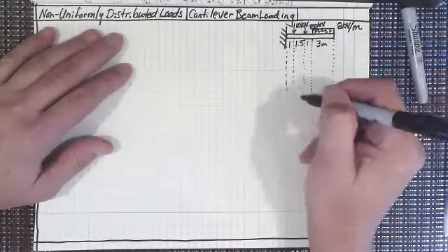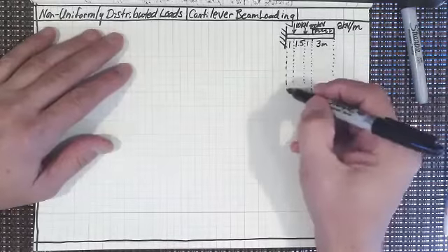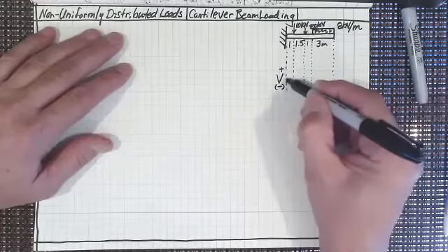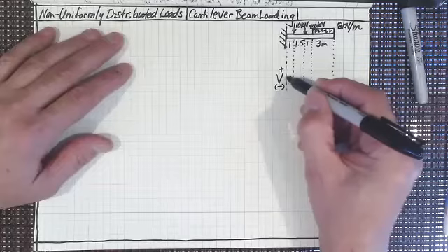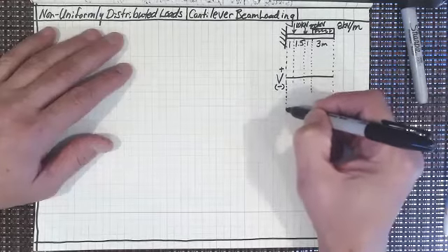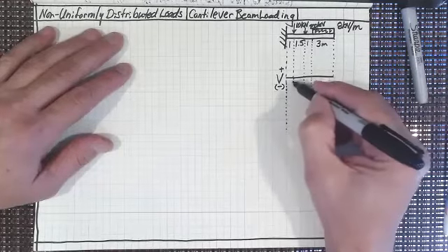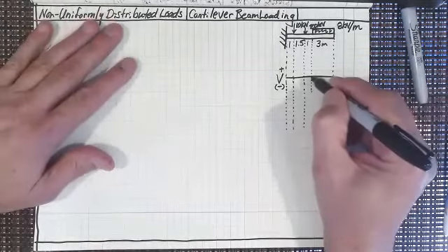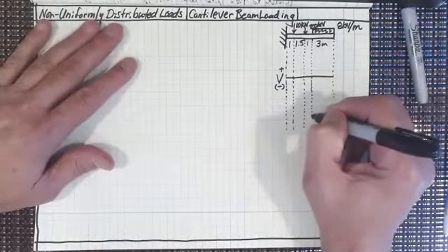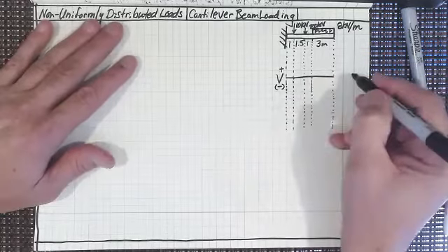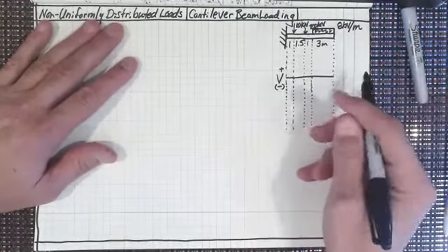And then let's say that this is going to be my shear force diagram. I'll put that down here. You're probably wondering, why did I put that down so far? And the reason for that is on a cantilever beam, just about all of the shear force is going to be positive, right? Because it has to be, because you have to be going up from a negative slope for the bending moment diagram up to 0, right? Because at this end, it's going to be 0.